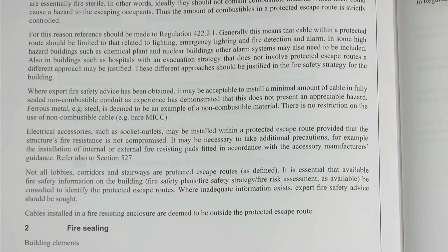And again, you may need to install things like fire resisting pads in those. And as we saw previously, putting in things like plastic mini trunking, say in a stairway, is really not an appropriate choice, because that gives off huge amounts of black toxic smoke and gases when a fire occurs, or even when they get relatively hot. So it's really just thinking about what you're going to be putting in there.